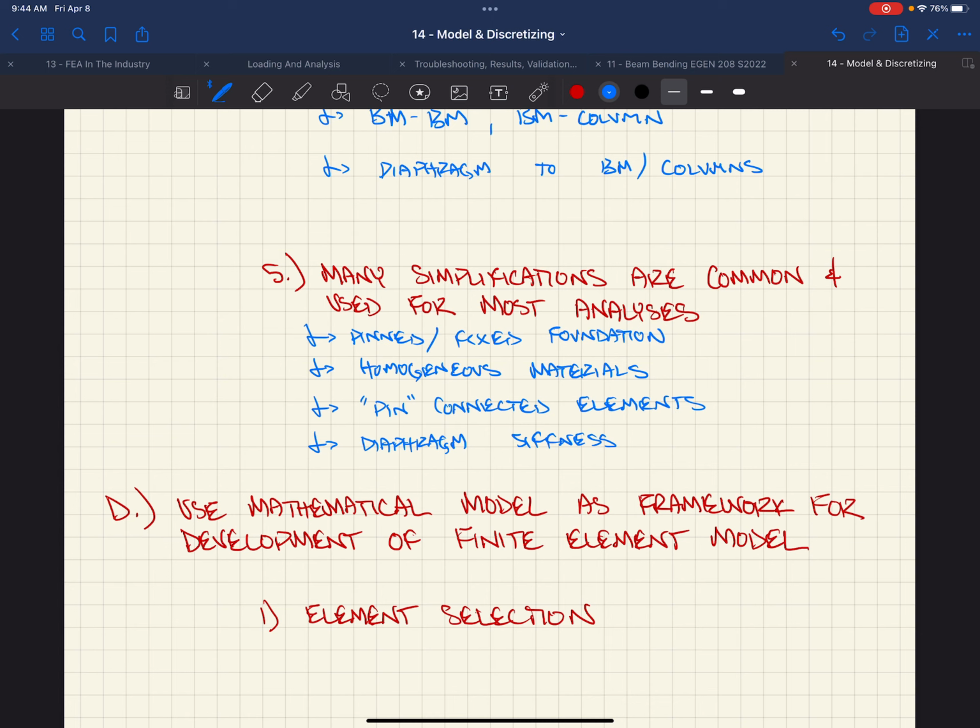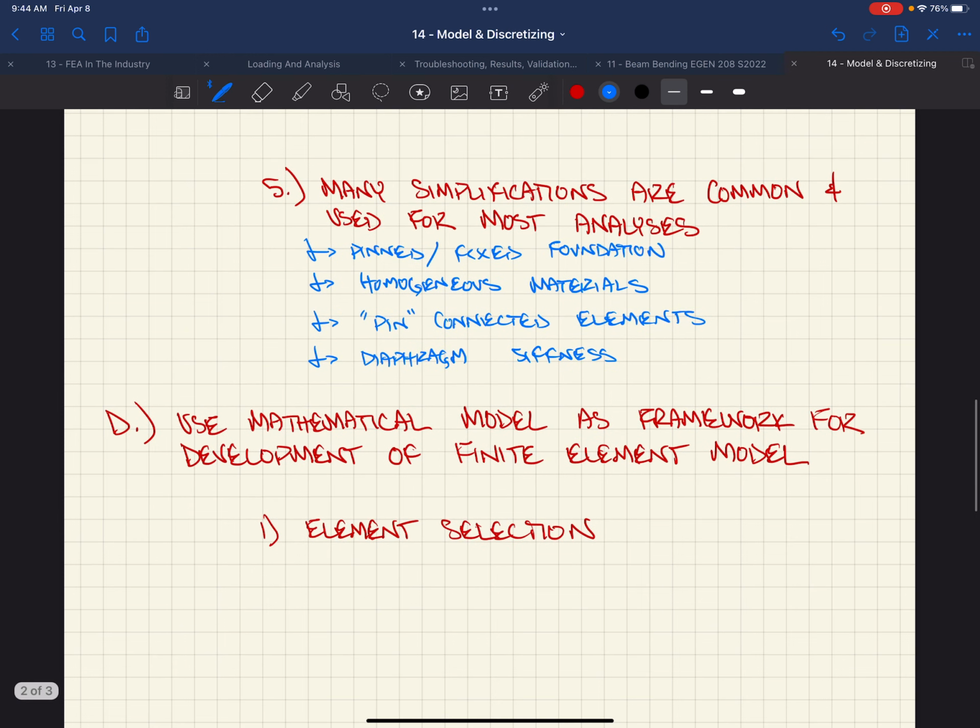So it's interesting, right? Those are huge simplifications that we can make with respect to modeling, taking the real world and making simplifications out of it, right? Especially when it comes to diaphragm stiffness. So we make those assumptions all the time, right? Not that they're right or wrong. That happens all the time. I've done it where I've done just tributary area. A lot of times though, by the end, I started doing this a lot, where you just model it as a continuous member. And it's really easy to do. You just put a continuous member. It doesn't matter how big it is. It just matters that it's all one stiffness, right? And you put a uniform load on it, and you look at the reactions in VA, and boom, you've got what your shear should be at each of your walls.